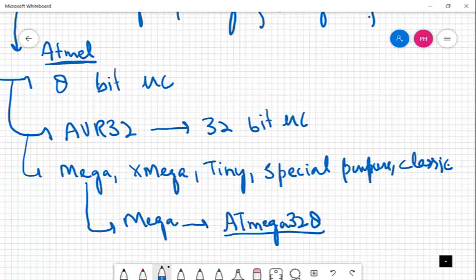Previously at IUST we have been teaching 8051 microcontroller, but the 8051 microcontroller is not used now in applications. It has no ADC, the speed is also less, the emulators and compilers are not also available, and it has not got a large peripheral set, like there is no ADC present in 8051. So I believe it's wiser to study Atmega 328.